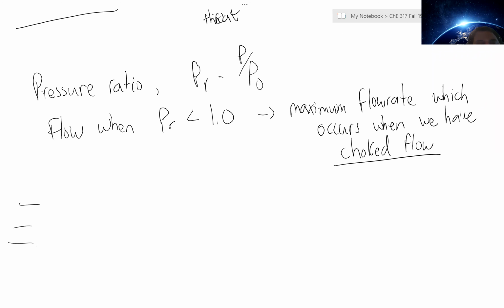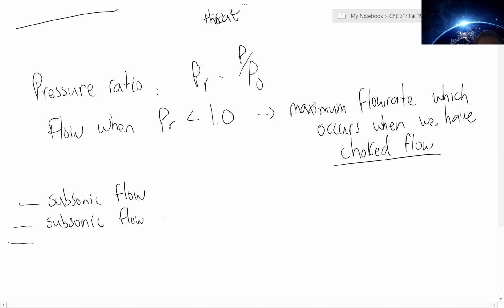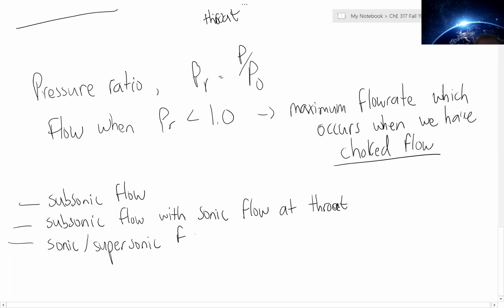You can have subsonic flow, then subsonic flow with sonic flow at the throat, you can have sonic/supersonic flow in the diverging section.